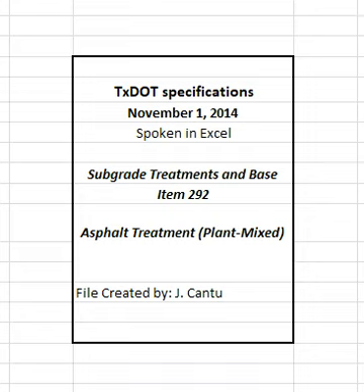Produce a trial batch using the proposed project equipment and materials in a large enough quantity to ensure that the mixture is representative of the mixture design. Within one full working day, the engineer will sample and test the trial batch to ensure that the gradation, asphalt content, and strength requirements in Table 4 are met. The engineer may waive trial mixtures if similar designs have proven satisfactory.